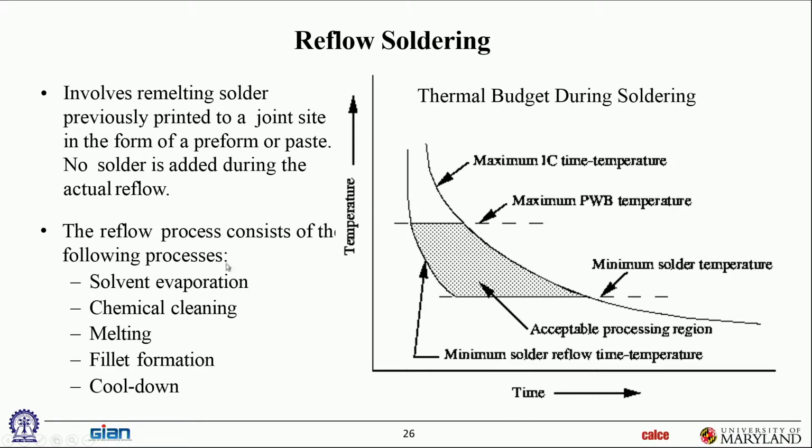Okay. And actually leading up to that process window is a preheating cycle, which we'll see soon. The preheating cycle is to prevent all the components from going through a thermal shock, so preheat a little bit. Also bake out any moisture that had collected in storage in the PWBs and in the components. You want to bake that out. If you don't, when you do that big spike to that temperature range, which is 230 degrees C or so, we talked about it in the last class, what happens to all that moisture?